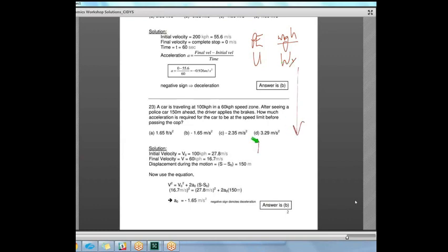And by the time it hit the ground, all that potential energy was converted into kinetic energy, which is 1/2 mv squared. That gives you your impact velocity to use with the coefficient of restitution to figure out the rebound. There are sample problems on that in this problem set. It'll kind of take you through that process.